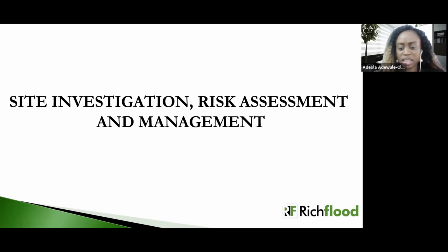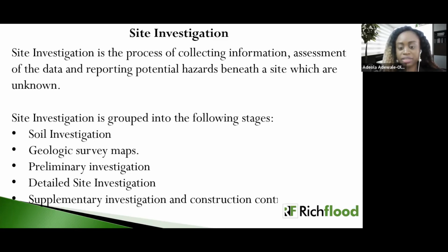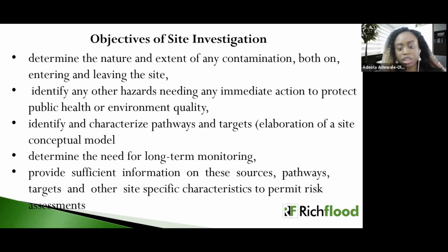Therefore, site investigation has a number of objectives it needs to fulfill. But before we go to the objectives, there are different stages in the site investigation procedure. We have the soil investigation, the geologic aspect of it, the preliminary investigation, a detailed site investigation, and even supplementary investigation and construction control. Now, the objectives of site investigation range from determination of the nature and extent of contamination,